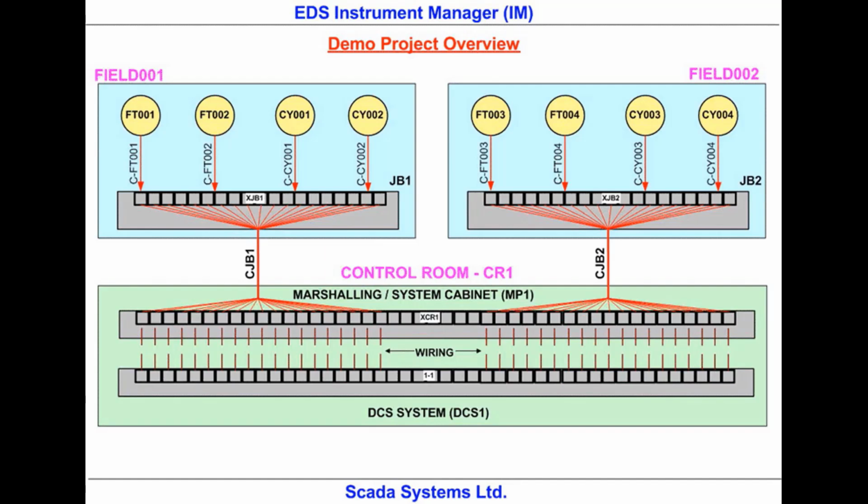control room. There will also be a PLC cabinet in the control room, DCS1, and inside this I will place an 8-input analog I/O card. I will connect wires from the marshalling cabinet to this card. After connecting wires and cables to devices and terminals, I will show the deliverables output, such as loops and datasheets